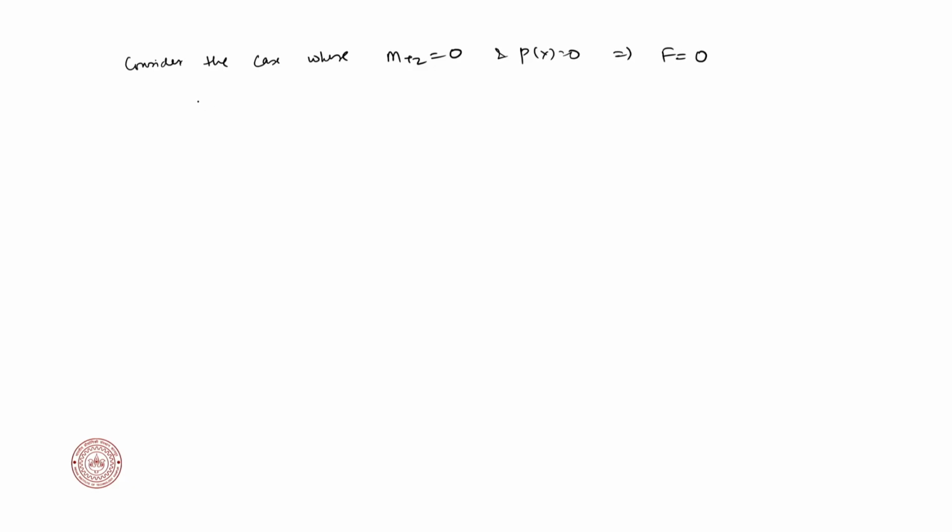So, our equation becomes EI d4v/dx4 plus P d2v/dx2 equals 0, or d4v/dx4 plus k^2 d2v/dx2 is equal to 0,